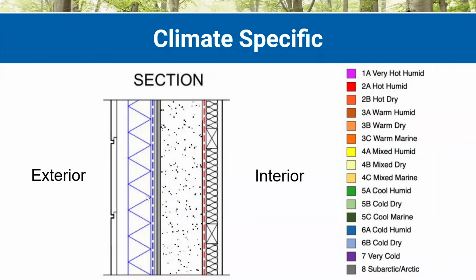For dry climates or marine climates, I am comfortable with that exterior being quite vapor open or vapor permeable. So you could be using the Solitex Mento membrane over plywood or the Adhero 1000 membrane, which has a higher permeability than the Adhero 3000. So that'd be more like in your climate zones 3 and marine.